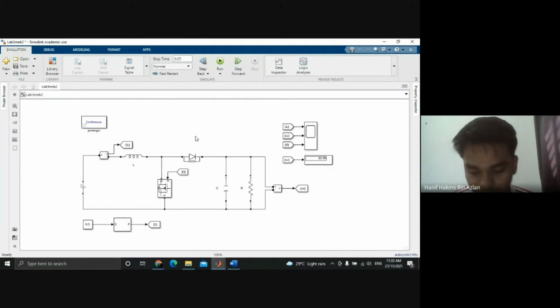I will continue to explain the lab activity for questions number 6 and number 7 Roman. For number 6, given the specification and all calculated values from 1 to 5 Roman, construct the model of the DC to DC converter using MATLAB simulation and plot the duty cycle, inductor current and output voltage ripple. For number 7, increase the minimum inductor by about 10 times to ensure full continuous mode, execute the simulation with the new inductor and fill in the table given in the question.